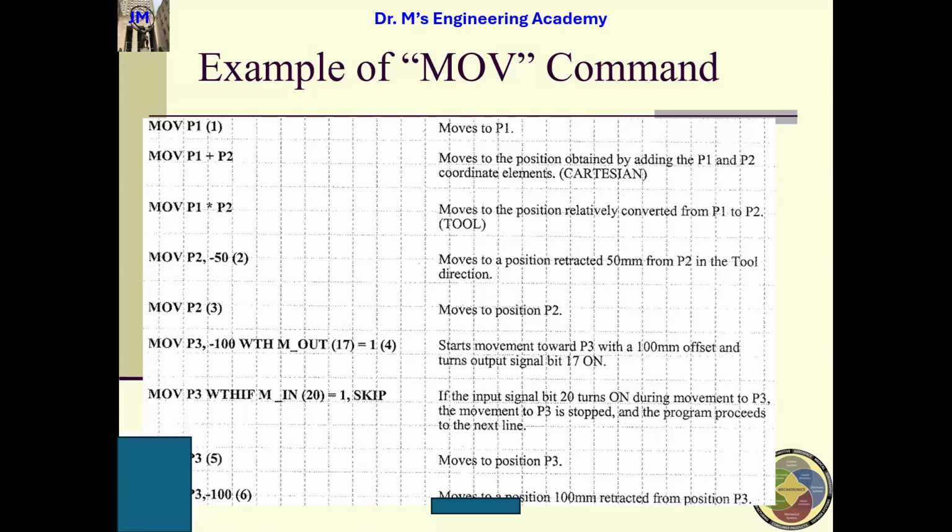And keep in mind, guys, in this example we use MELFA BASIC 4. Okay? The subtle difference between MELFA BASIC 4 and MELFA BASIC 5 is that for BASIC 4, we use minus 50 to mean vertically above the desired location. Make sense? Because a lot of customers gave feedback to the Mitsubishi company; they wanted to say minus is going down and positive is going up.